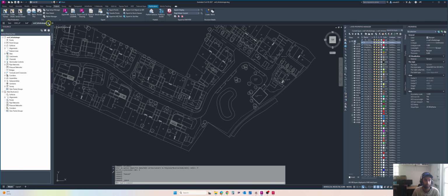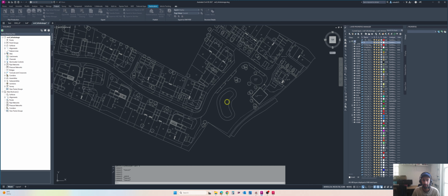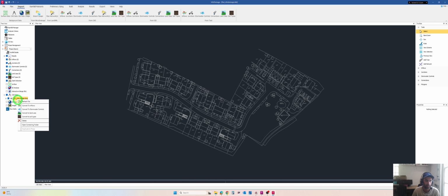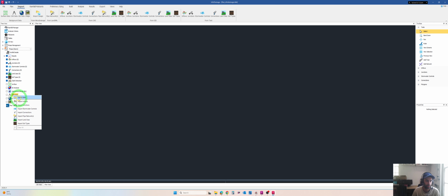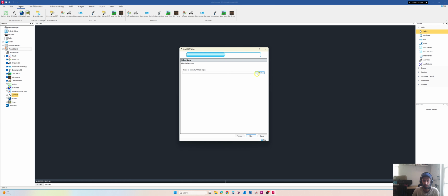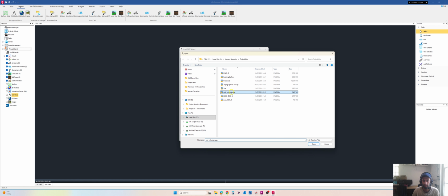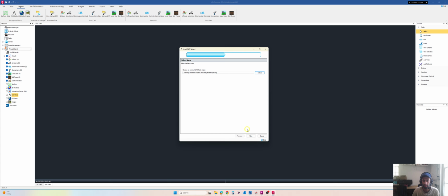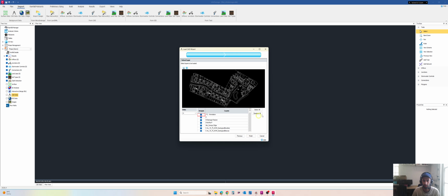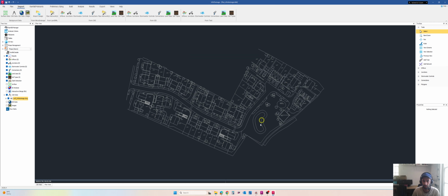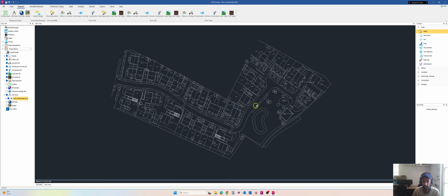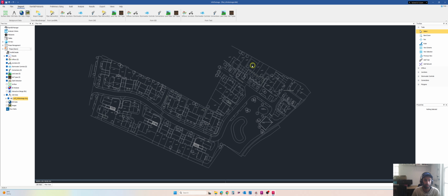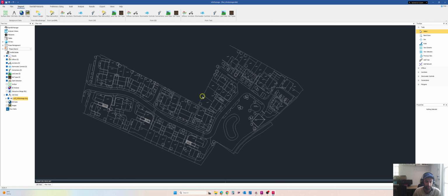Yeah, we can just remove this one, save, and we can remove and re-import. And this one will be Xref InfoDrainage. And again, deselect all, only one layer. That's this one. Now we have the pond location, we know a bit of the route, and then quickly save this drawing. Control S for the save from here.